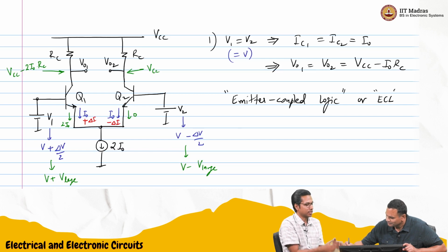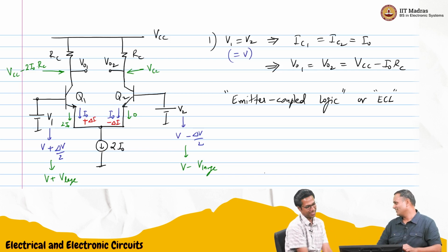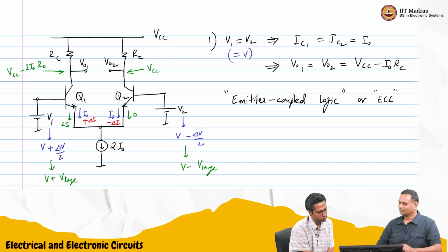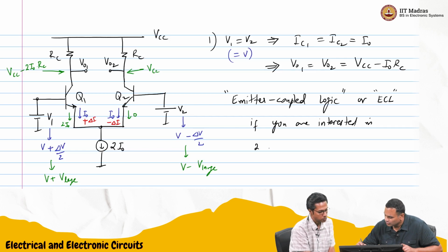Also very nice. So with the same structure, I can use it as a difference amplifier, or as a logic gate. So you do this if you are interested only in two levels, VCC and VCC minus I naught RL.